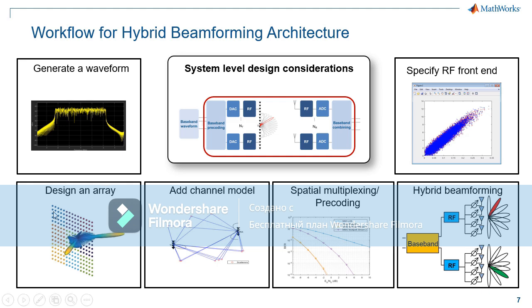You have to design antennas and antenna arrays that enable you to achieve those narrow beams that participate in the process of multi-user MIMO, massive MIMO structures. You have to have a representative channel model with lots of scattering included in order to make the essential estimation of the angle of arrival, angle of departure, the locality of the transmitter and receiver, all of that possible.